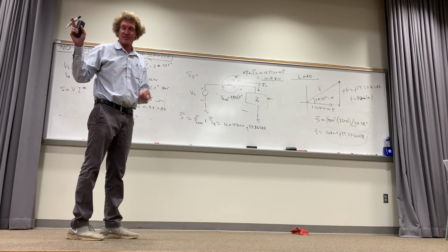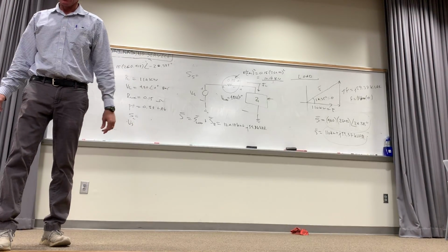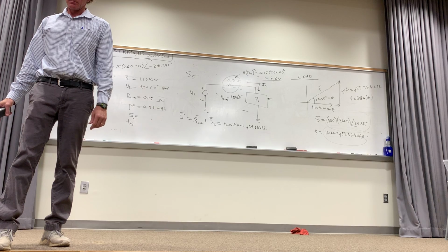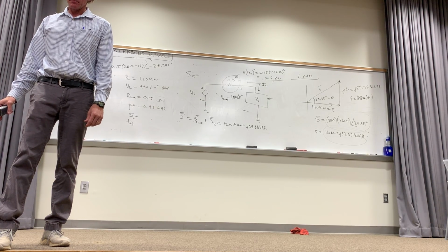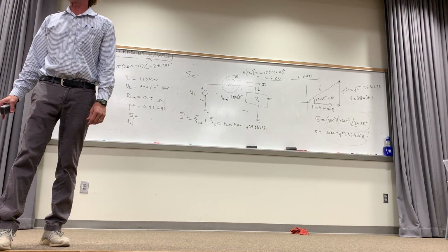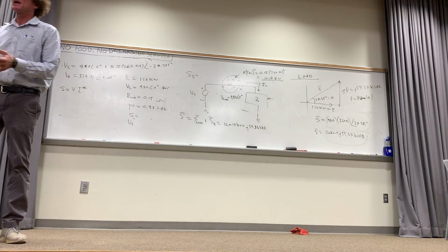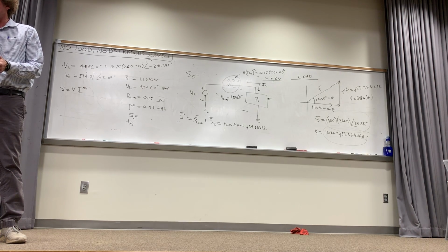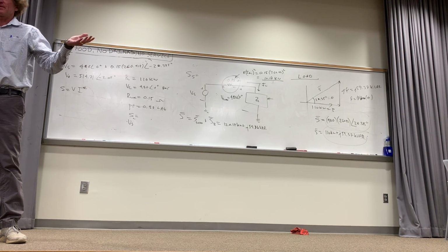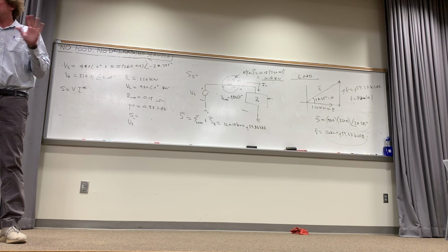Just sorry, there's one other question about that. Is that equation saying that the J portion of the power goes to the resistor, or no? The imaginary part is only associated with an element that doesn't dissipate power. When you have a J 57 kVAR or something like that, that's never dissipated.